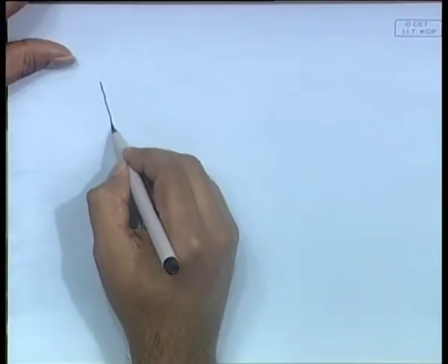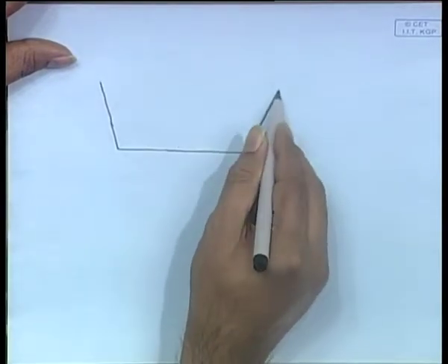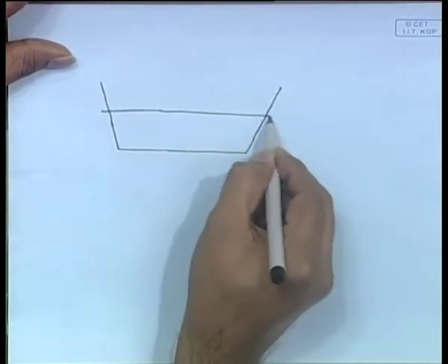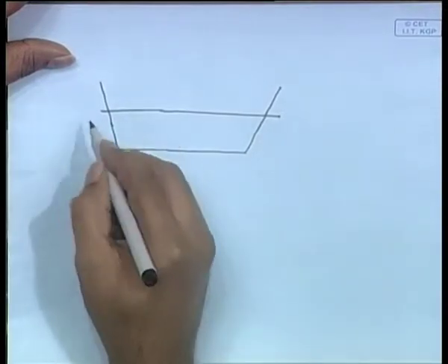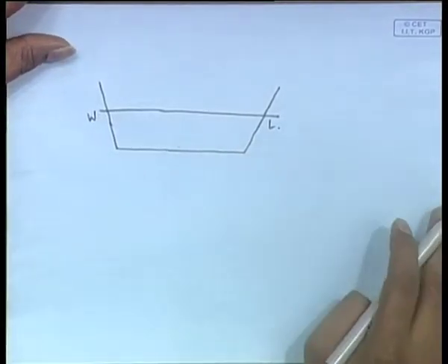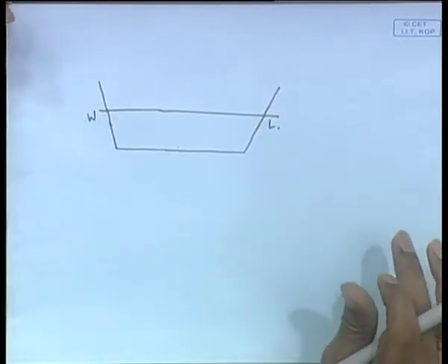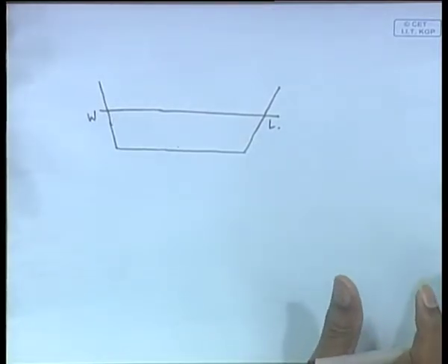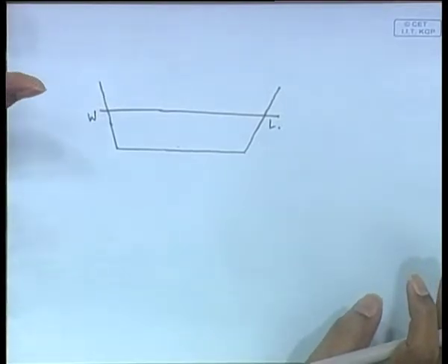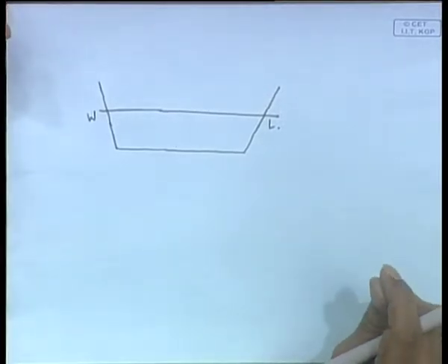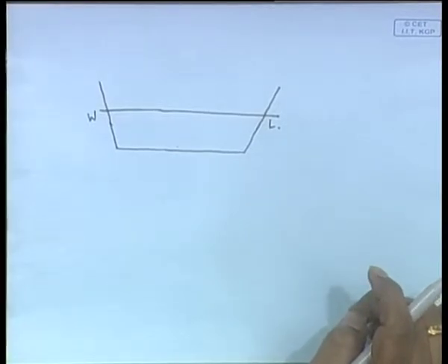We have to bring in the concept of waves because this lecture is definitely on waves, but let us do it without waves first. So, this is the shape. Now, this is a water line. What are two important points that we can definitely assume in the case of a ship that is floating like this? First, you know that the Archimedes principle holds good. Archimedes principle says that the weight of the ship should be equal to the upward force, which is called the buoyancy. Now, how do we get the weight?